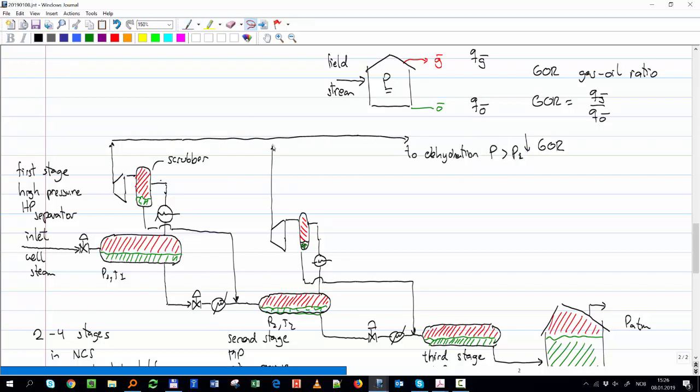The thing is that the compressor is a component that uses a lot of power, and the power is, in principle, driven by the difference in pressure between inlet and outlet. Even though here the rate might be very low, in every stage the gas that I take becomes smaller and smaller, typically. But here the delta P is higher, because I have to go from P2 all the way to P1, to P dehydration. So to avoid that high power requirement, I send it to the compressor of the first stage.